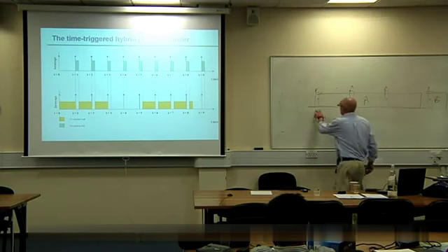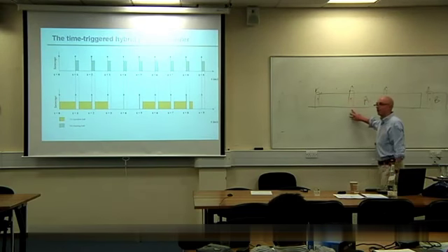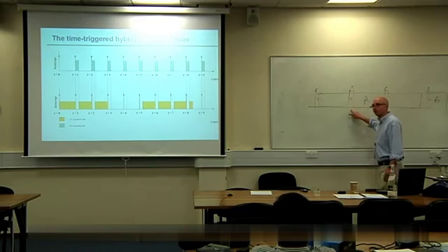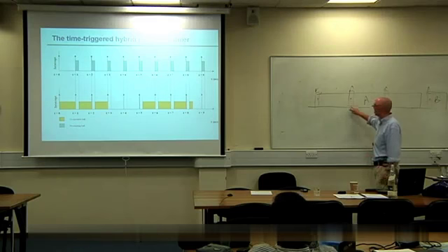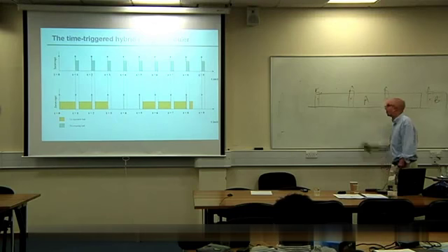Typically, I'll make this task very short. The kind of thing you might want to do with that is take a sample from your ADC. You need to do it more frequently, but this long task gets in the way. Why not just interrupt that task? Very briefly, we know the ADC sampling takes a couple of microseconds. So if we were to allow a 5 microsecond block, that wouldn't make much difference to the overall load on the system, and we could comfortably take an ADC sample in the middle of this.